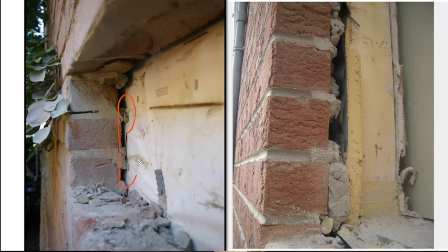So when somebody says, I want a 3 millimeter gap, more than a 3 millimeter gap behind my cladding, well, in this drawing on the right, we definitely have more than 3 millimeters. That is about a 20-some millimeter gap, but it's filled with mortar and blobs and so on because of the nature of the construction. Now, you can properly argue that the mason could do a better job, but it's really